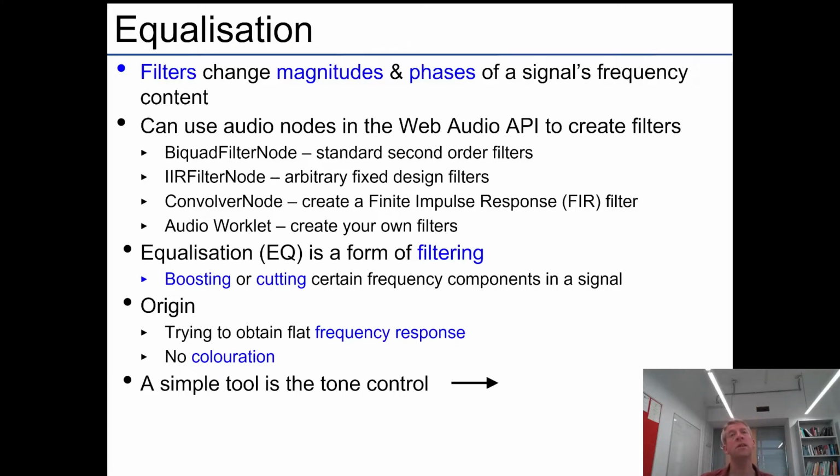So they boost that high frequency content with some filter in order to keep a flat frequency response, where the frequency content at the output is equal to the frequency content at input. So it's equalization. Another term that's often used is to say that the content is colored if the frequency content has been significantly changed. So the goal is no coloration of the frequency content.